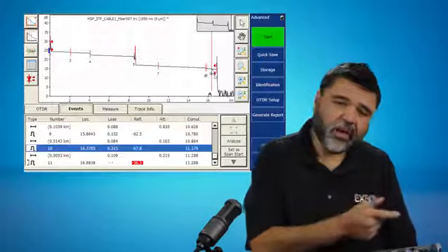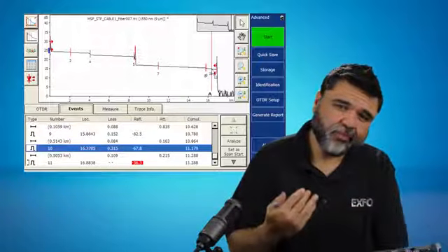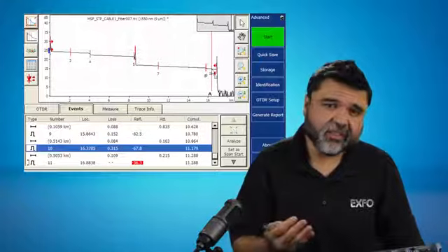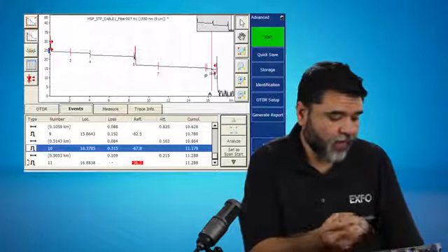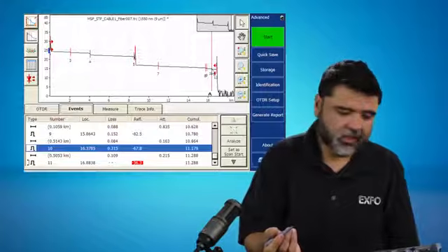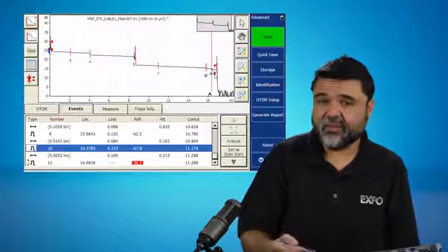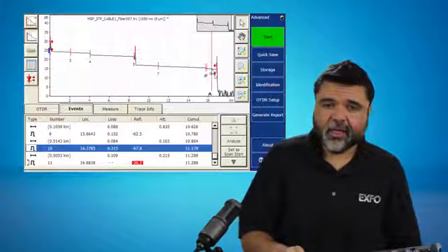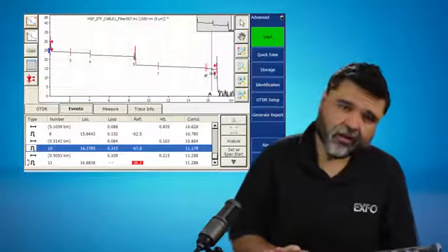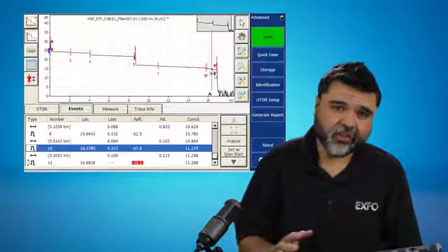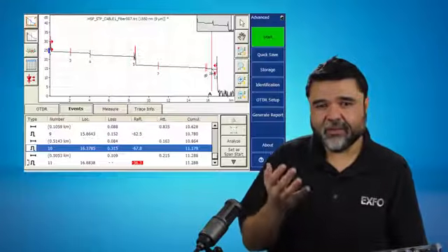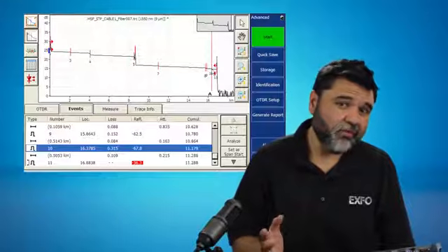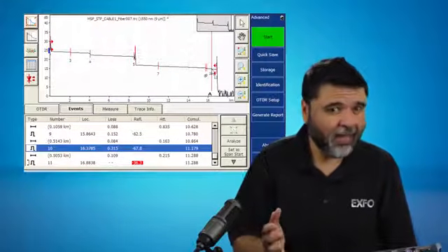So for this type of connector, again, I expect 0.5 dB of loss and about minus 60 to minus 65 dB of reflection. So if I look at it, I have 0.3 dB of loss and minus 67 dB of reflection. So I'm very happy. So this is a nice, good connection. And so this is very important to understand. When I ran an OTDR as a technician, I always used it to find the backhoe sticking up out of my cable. What I never used it for was to find a dirty connector or a bad connector.